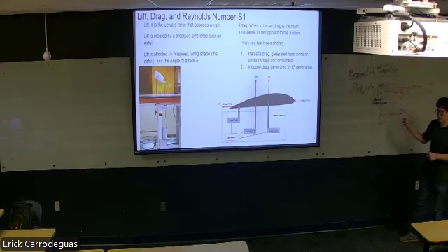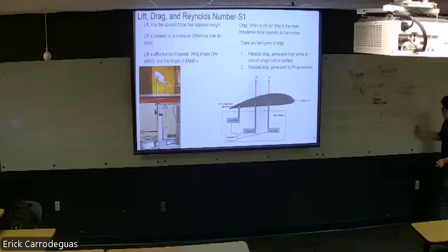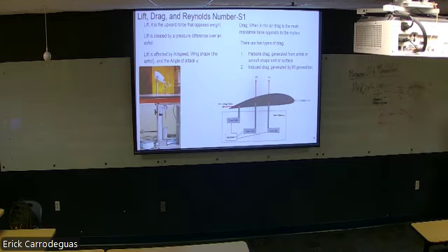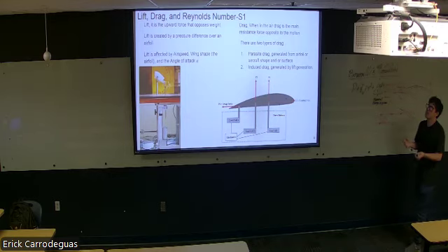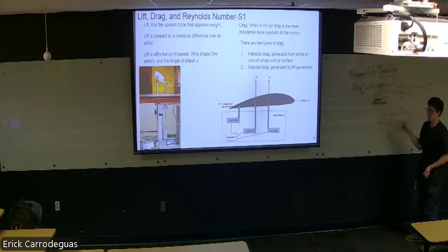So in order to stop this, what we've done, and you'll see this in airlines, is add winglets. You have the plane up front, you have the wing, but you have these things pointing up or down. And instead of the airflow going down and having a vortex here, it causes that drag that's happening to go up here. This is on some planes. The plane wings that we have in the makerspace are elliptical, so you don't really have this issue with them. It just gets dissipated out as it goes down.